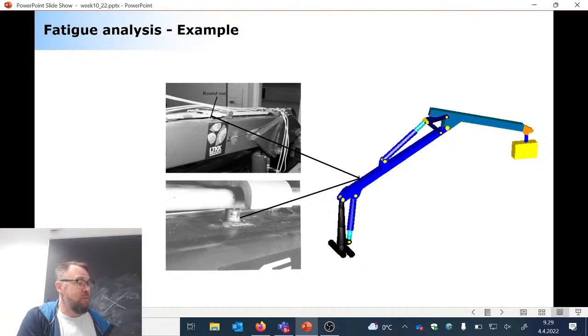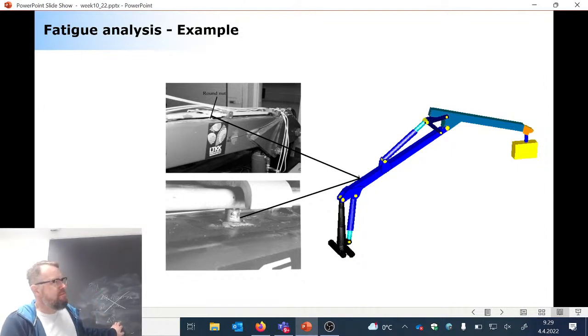By the way, welding of aluminium is even more cumbersome, because in steel there's a threshold loading, this equivalent loading, this one here. When you don't really see the fatigue anymore, you can make a safe assumption that the fatigue life is forever. So it's not going to fail in your lifetime, not even your children's lifetime. But in aluminium, it's going to happen eventually. Of course, it can take years and years and years, but aluminium is behaving in an unpleasant way in terms of fatigue.